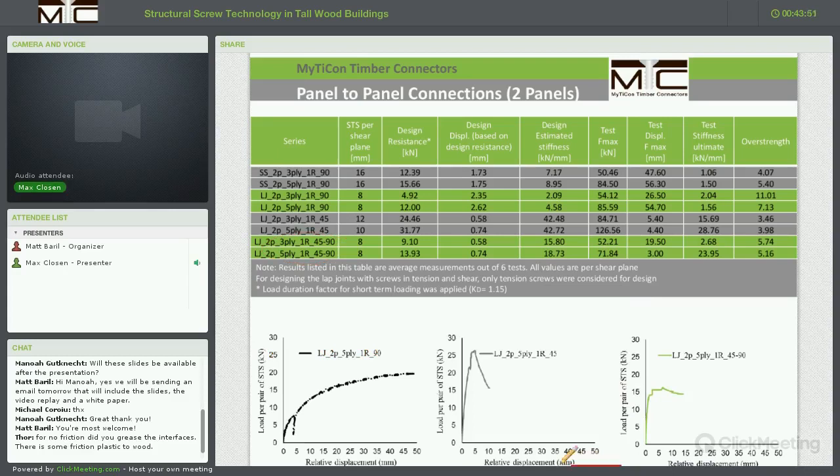Towards the end of this presentation, we just want to show the different performances again of fasteners loaded in half-lap joints, where we have a relatively reasonable stiffness increase initially, and then a curve that keeps flattening towards more displacement at the end. All connections where fasteners are used in tension have a stiff performance with a fairly steep load drop towards the end of the testing. For the connection systems where we have a combination of screws, 45 and 90-degree screws, screws in tension and screws in shear action, it looks like we get very good initial stiffnesses and still are able to maintain some sort of displacement and ductility for larger deformations in this area.